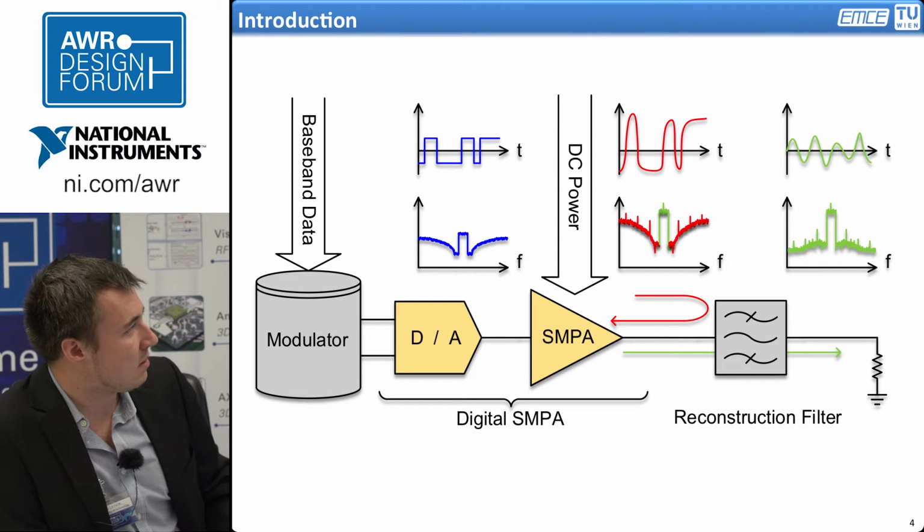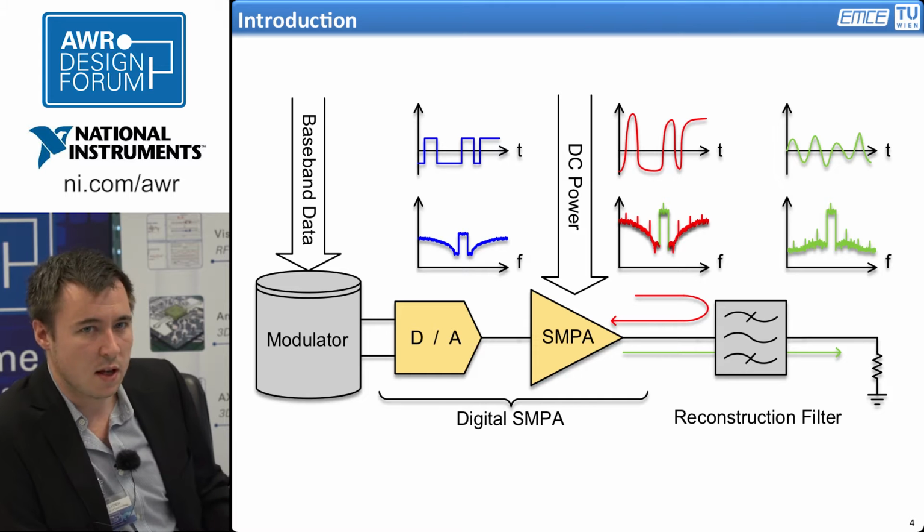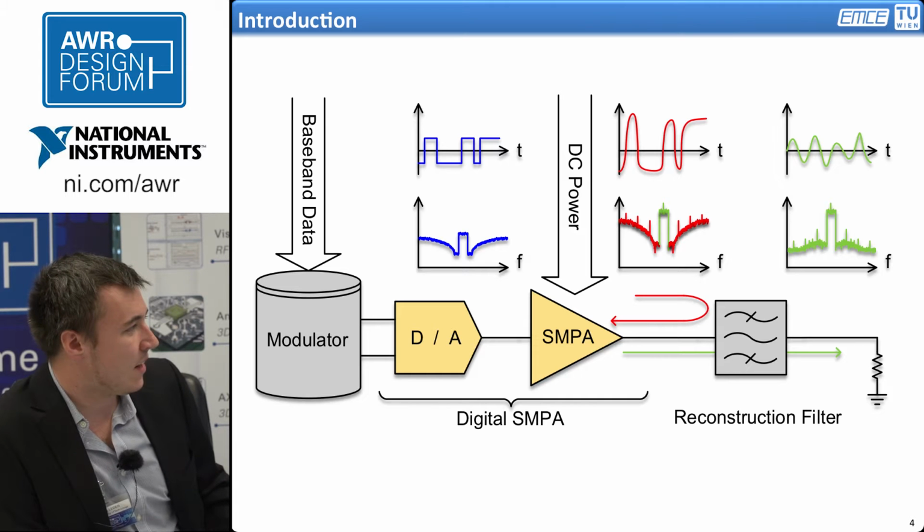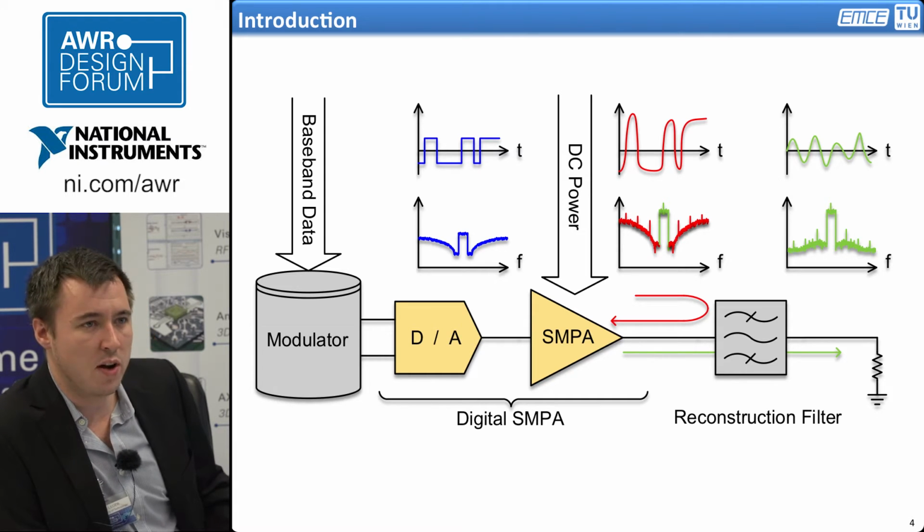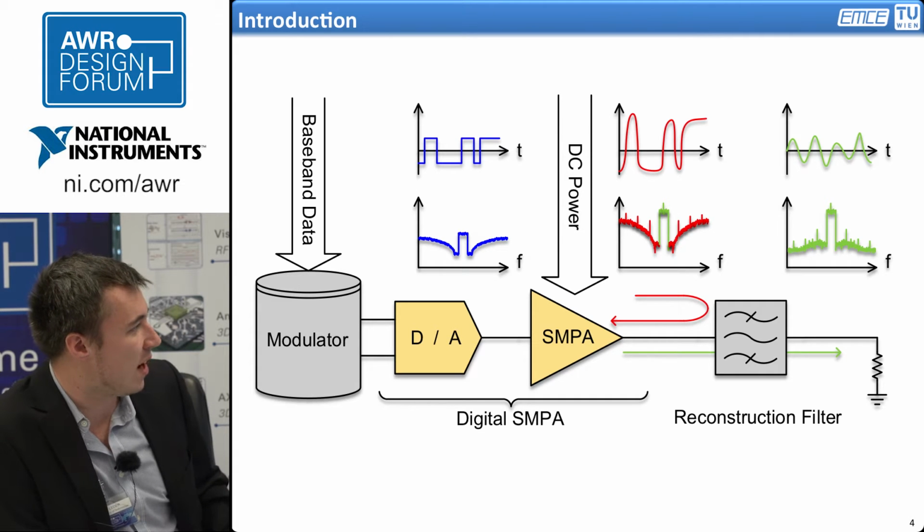And since this is basically a constant envelope signal, since it's binary nonetheless, we at least in theory could amplify it very power efficiently using switched mode power amplifiers in order to have a power efficient system.